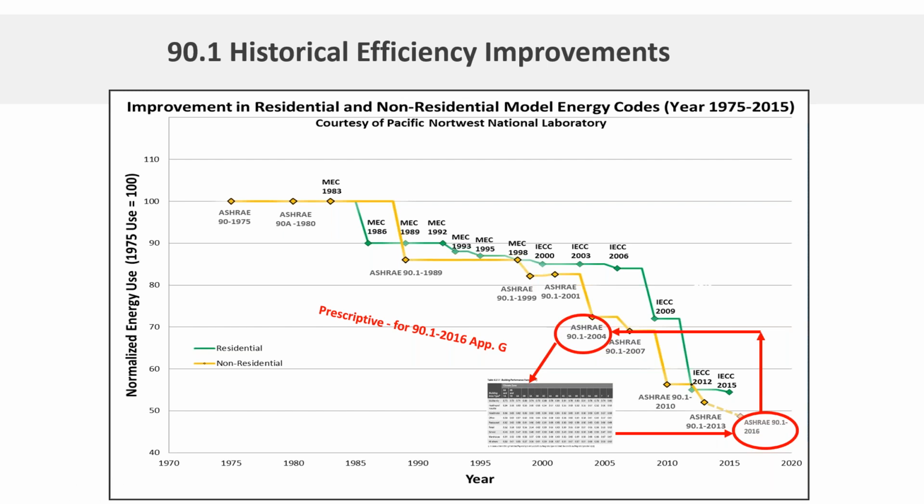The intent of the standard is to drive energy efficiency towards net zero. That's the overall goal of 90.1 and ASHRAE generally for commercial buildings. And obviously there are some limitations to that, including cost and feasibility for certain climate zones to get to that point. So there are discussions of what the next steps will be for the next iteration of 90.1 currently going on. But renewables do become part of the standard. There's a minimum amount of renewables required going forward.